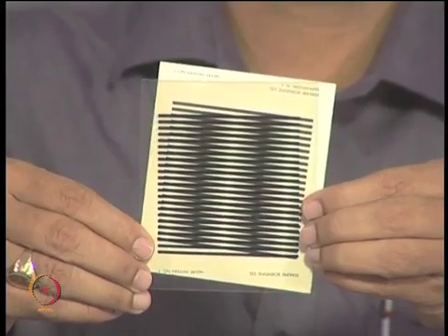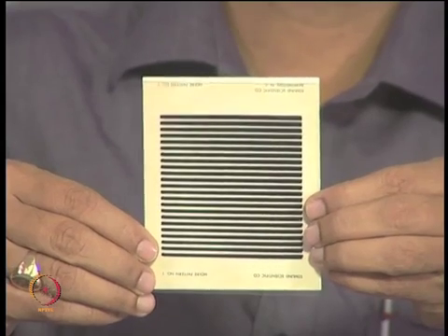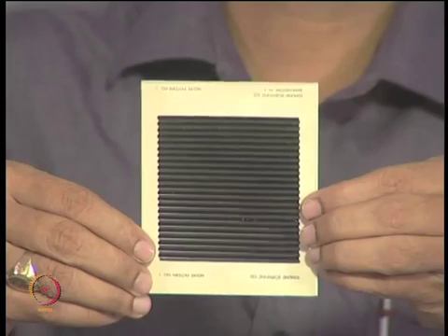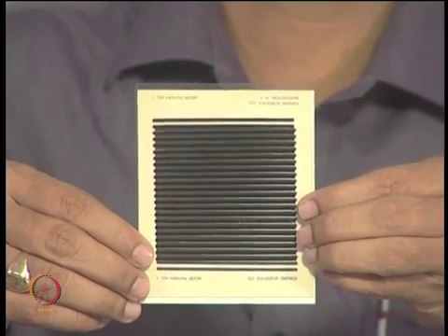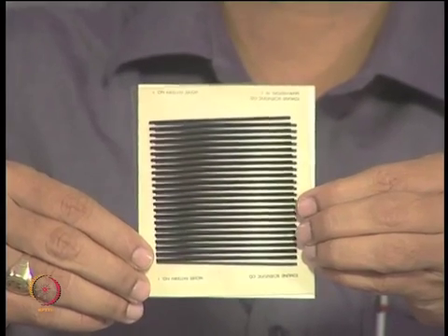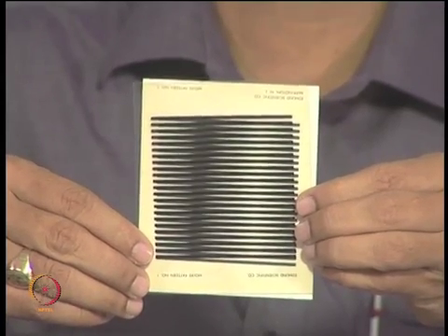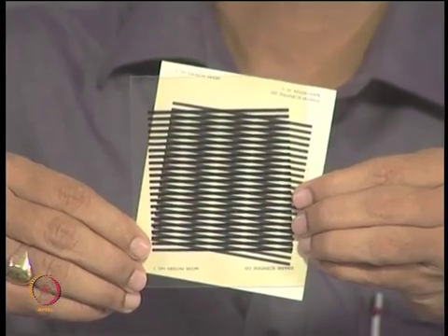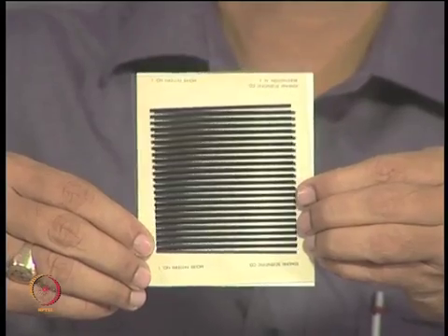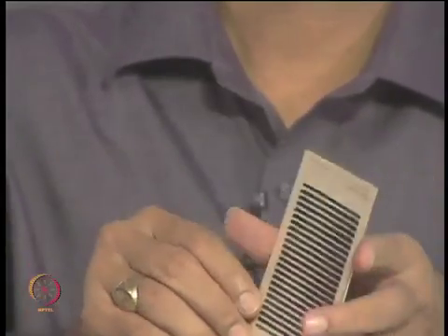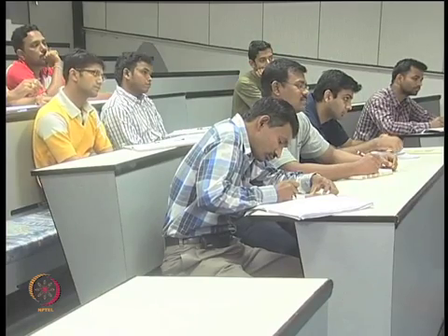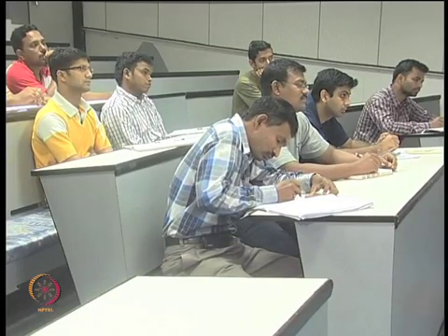I see fringes, we get excited to see fringes, but you should implicitly understand this is a nuisance in Moiré, because in Moiré I would like to find out what is the effect of stresses or strains introduced in the material, not rigid body rotation and rigid body translation. So, you will have to be very careful while performing Moiré that you take care of the effect of rigid body translation and rotation. It is very important, it is very subtle, and we will again go back and look at it.